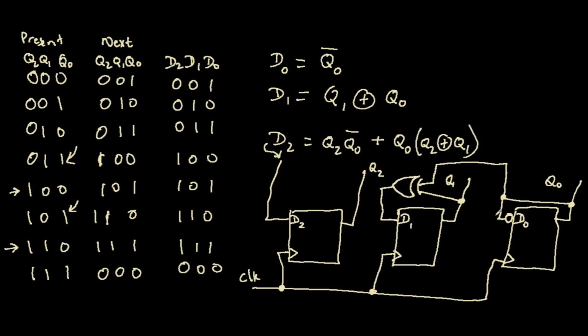So we're going to need some signals here. Now, these are things we should obviously have specified at the very start, but we're going to need some signals over here, and it will just make a lot of sense to have each of these being a signal. So I'll say S underscore D2. I'll connect a signal to each of the inputs, and I'll connect a signal to each of these outputs, so S underscore Q2, and I'll do that for each one of them.